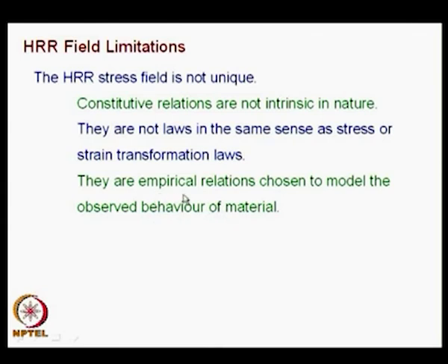The moment I say empirical relations, one could arrive at another set of empirical relations for the given type of data. So, from that point of view, the HRR stress field is not unique, and whatever discussion we do here applies to all empirical relations. In fact, in EPFM you see only empirical relations, because that is how the engineering community has found utilization of EPFM possible.